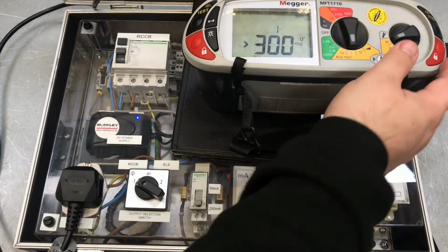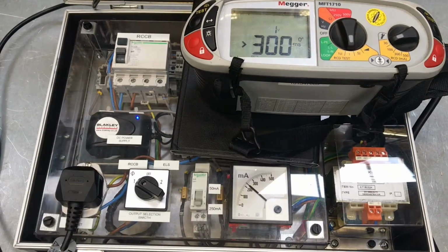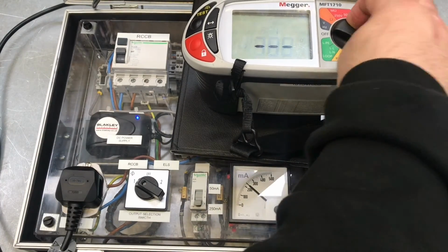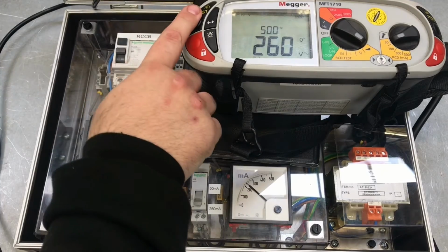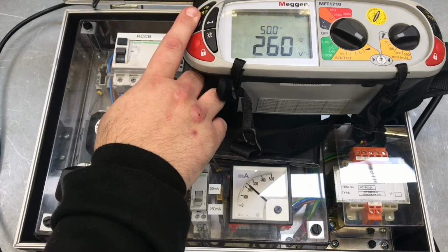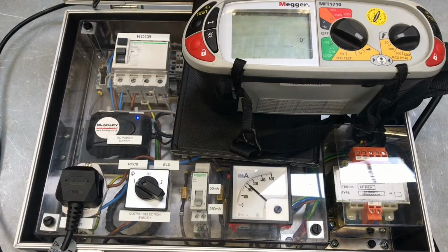So I'll tell you what I'll do. I'll do a ramp test to see if I can unseize it. Maybe there's something I'm not aware of. I'll do a ramp test and I'll see what comes of it, because the ramp test is a great feature. At this time we know there's a problem. I'm doing a ramp test. Oh no, and it's come back greater than 33 milliamps. So it's not tripping. It's gone past the rating of the RCD.